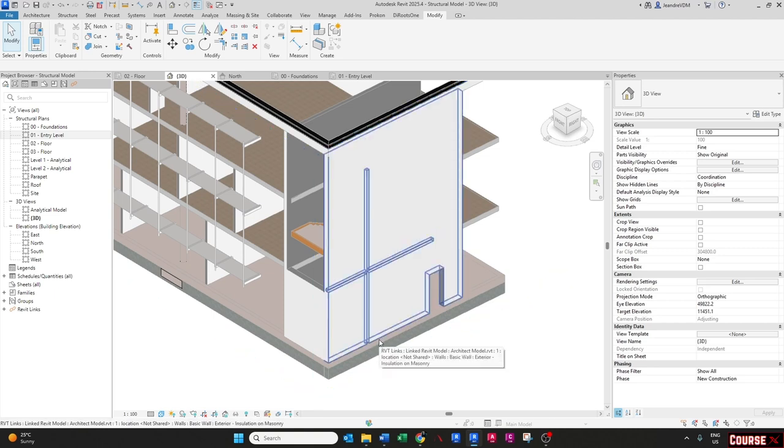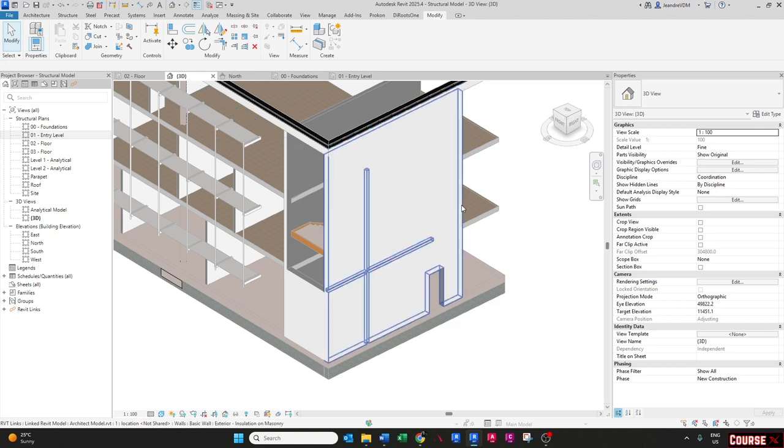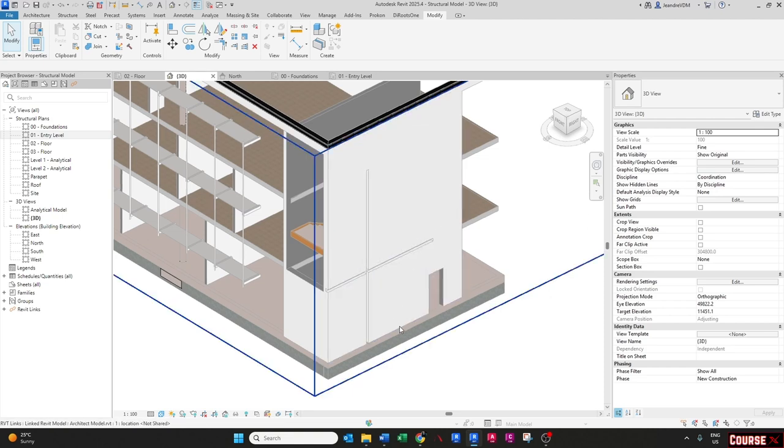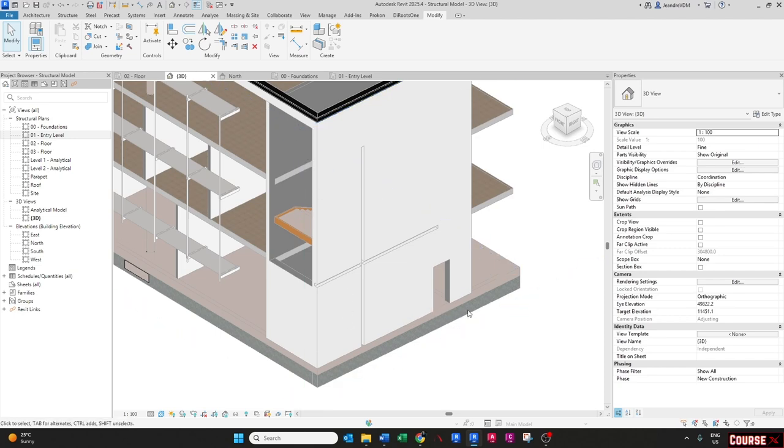And this is how I communicate to most of my architects that I work with: I will draw all the walls up to a certain level and he can do the rest of the walls for the building. If it's a load-bearing wall, however, I will draw in that wall fully or to the full extent of what is required, because then it becomes a structural element. But a wall is a structural element in a sense, but for this instance, it's just to close up this